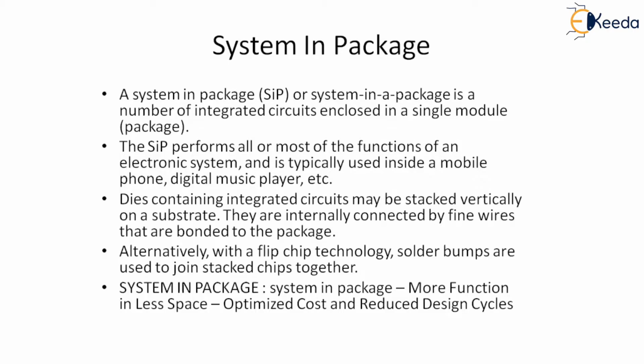The dies contained in the integrated circuits may be stacked vertically on a substrate, one over the other, and they are internally connected by a fine wire which is bonded to the package. Alternatively, we can use flip chip technology, where solder bumps are used to join stacked chips together.